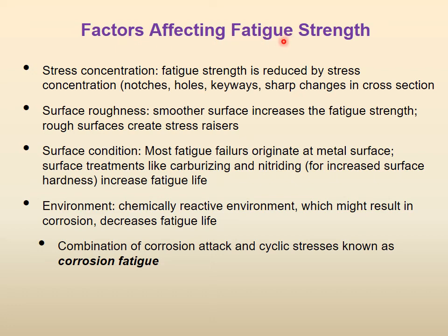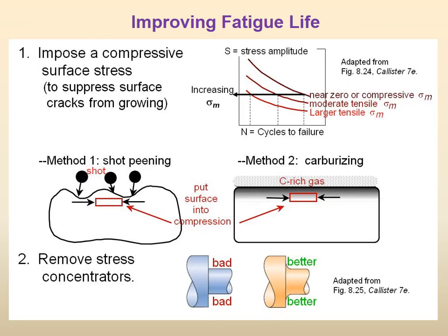So if we want to improve the fatigue strength, or if we want to delay failure due to fatigue, then we work on these factors. Can we improve the stress concentration? Can we improve the surface roughness? Can we do surface conditioning? Can we change the environment, and so on? So that is what we are saying, right? Improving fatigue life.